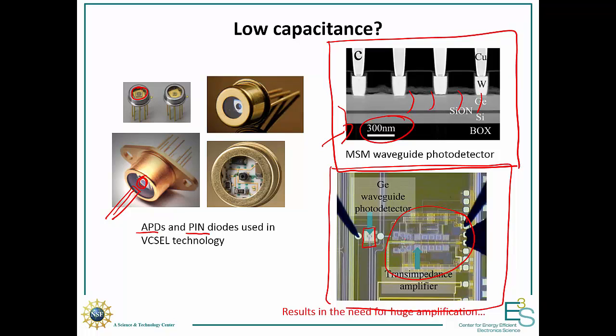What we're seeing right here is that you have to have a wire that's going to bring the signal from the photodetector all the way to the transimpedance amplifier. And what does that wire have? It has capacitance. Actually, the capacitance of a wire is approximately 2 picofarads per centimeter. That's also 200 attofarads per micron.